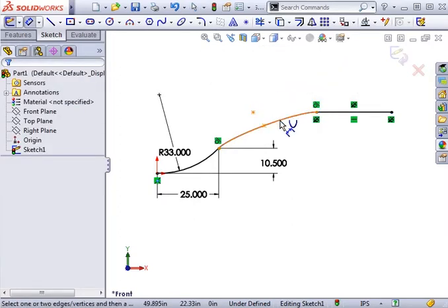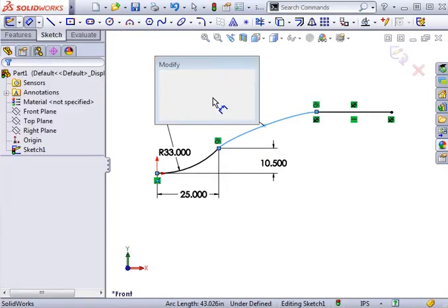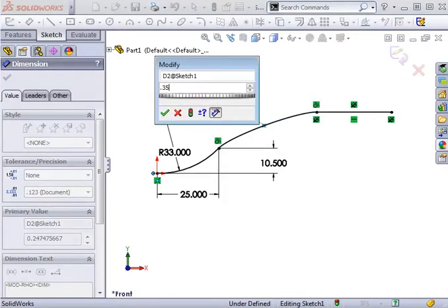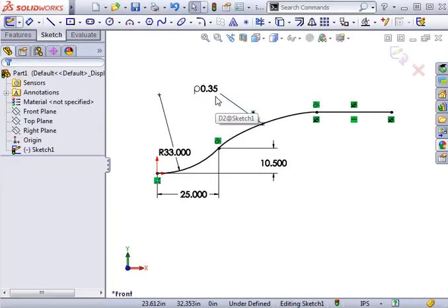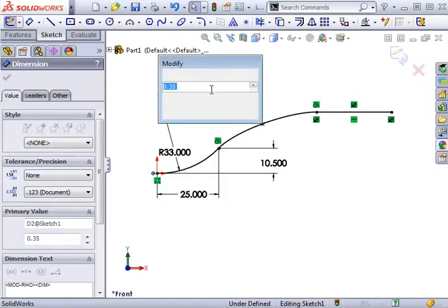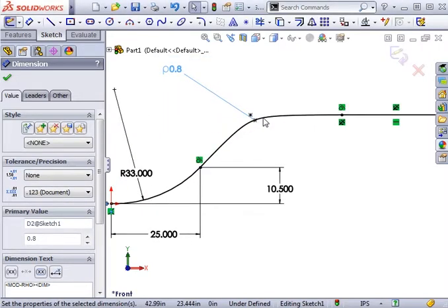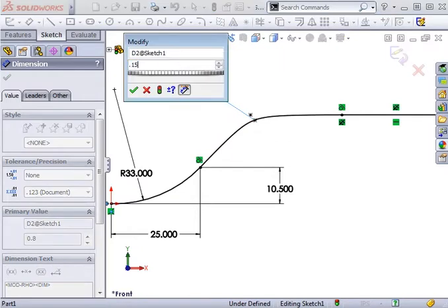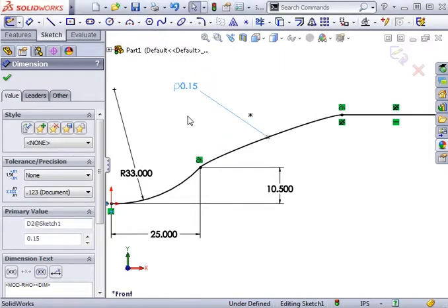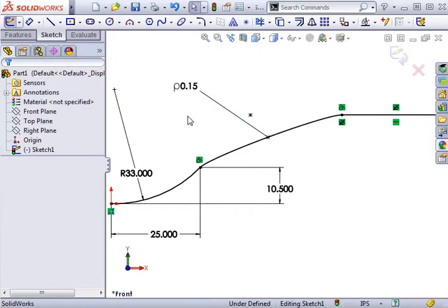Making the vertex tangent to both inference lines of the 2 curves is a good practice as well. But again, it depends on the curve that you're trying to create. I'd like to go into the rho value a bit more. Rho is a number between 0 and 1 that describes the relative angle of the plane intersecting the cone and a conic. High rho makes the conic sharp, while low rho makes the conic round. Conics are always planar and simulate the look of a C2 or G2 blend, or in other words, a curvature continuous blend. And since it's second order mathematically, there won't be any inflection points.